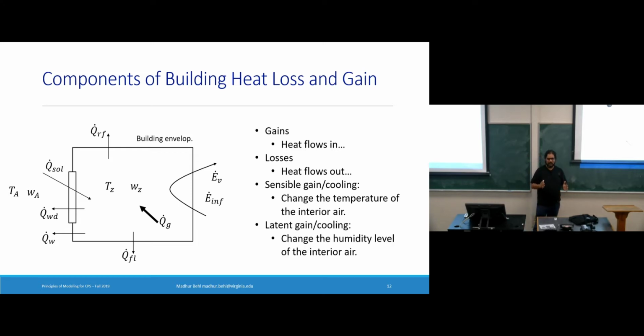Okay, so latent gain or latent cooling is something you may feel indirectly as discomfort, but mostly you can think of it as things like humidity changes. So when I'm speaking, and even when you all are breathing, we are exhaling water vapor into this zone air, which is changing the moisture content of this air.